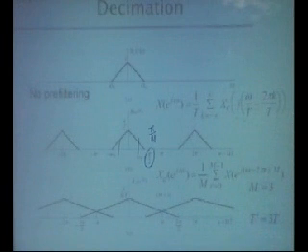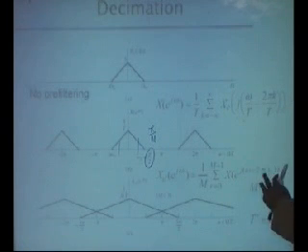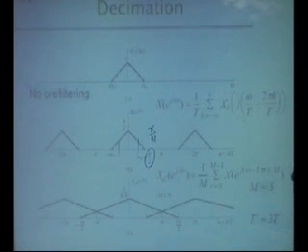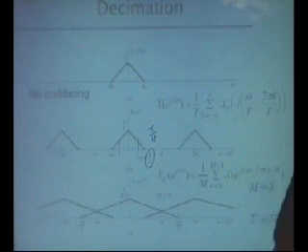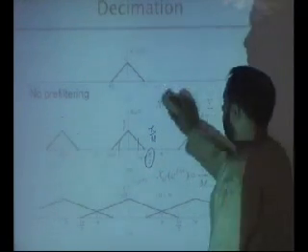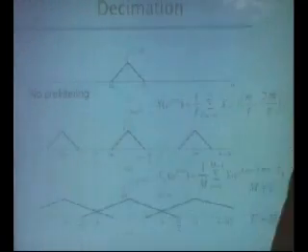Cut the frequency spectrum which perhaps I don't require, which is out of band, some other band coming in my signal. First throw that away, and then you throw away samples. Throwing away samples means compression in time and expansion in frequency. It's an inverse relationship, always an inverse relationship.